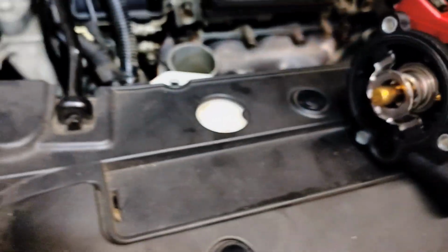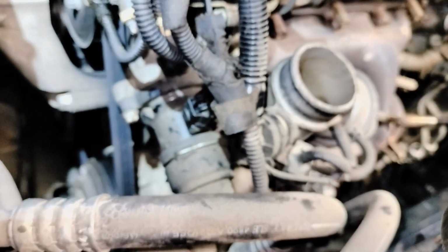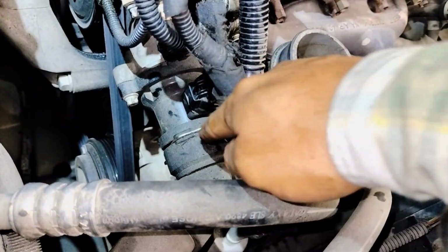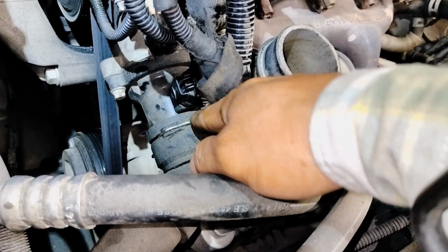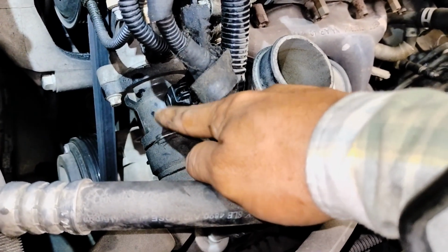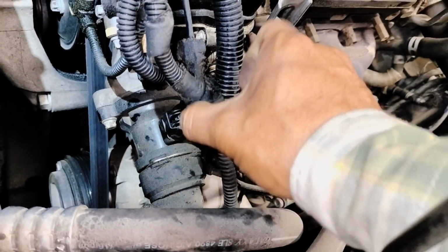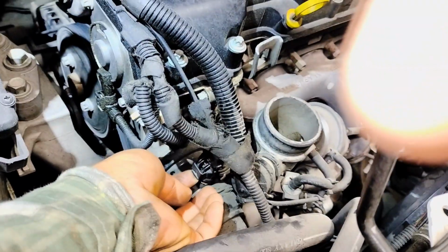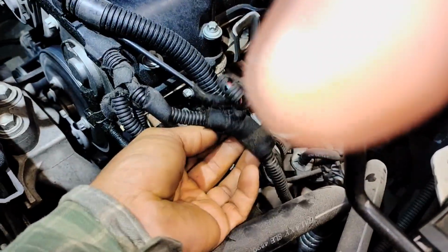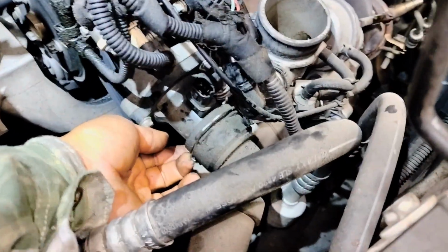I had already drained my coolant, and the next step is gonna be removing this little safety clip. We're gonna pull here with the pick. We're gonna pull it, then we're gonna remove the plug here. And the plug, I'm gonna pull here on the bottom and pull up like that. And for this, I can also stick my finger here in the back and do it like that here.